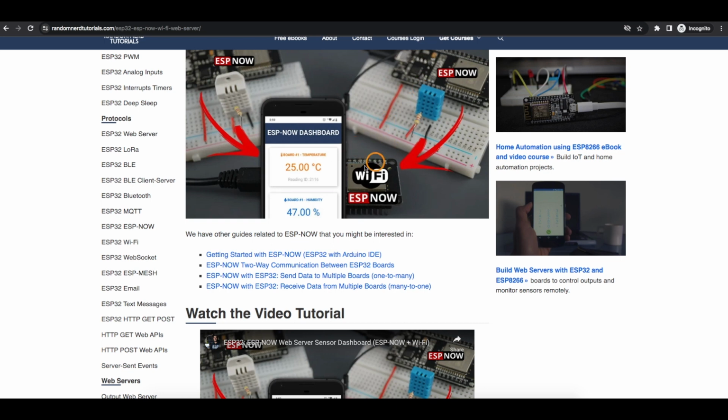And then, based on the status of each of the nodes, maybe that's the kind of info I would put on this web server. So just by following this project example, it necessitates one of the two modules being more like the master who's doing the web server. The other one's more like a slave, and having it set up this way, ESP-NOW does auto pairing, so I don't have to hard code MAC addresses and tell them exactly which module to look for. They can just figure it out between themselves.